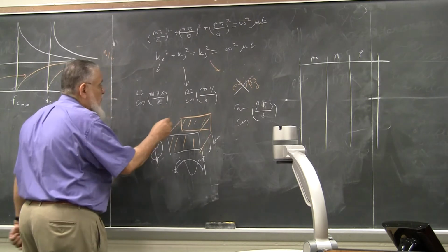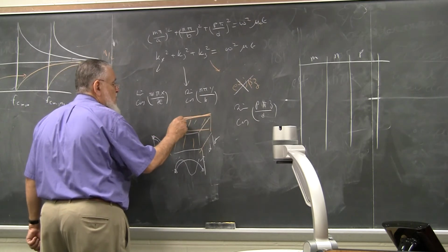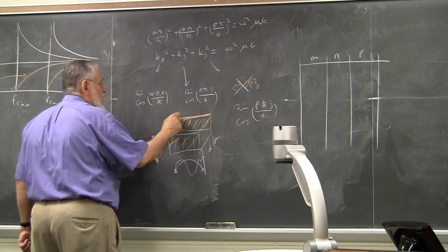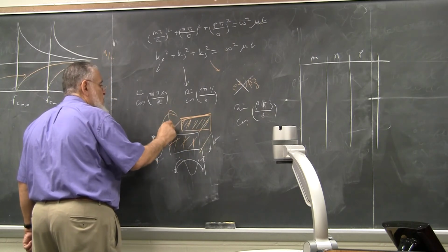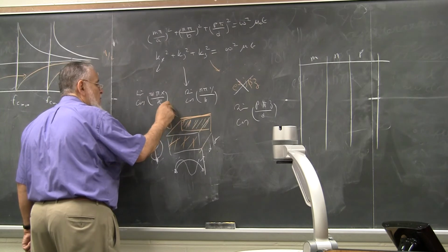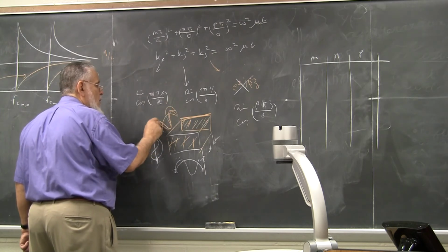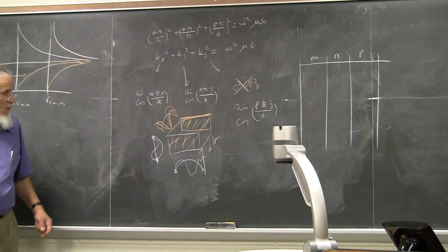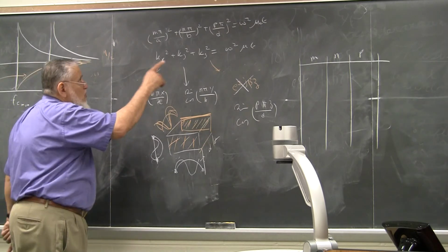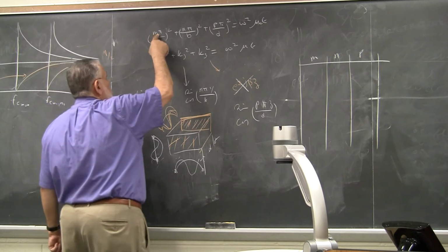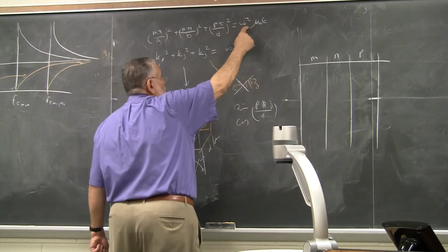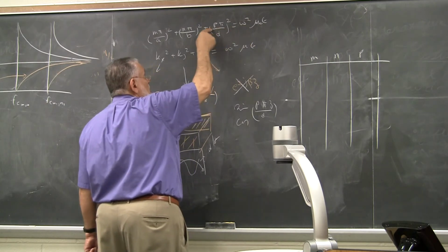On the d also, to meet the boundary condition, that means the field has to be shorted here and shorted there. That means again you have a similar situation, right? To meet the boundary conditions, again, p has to be an integer. So this must be an integer, this must be an integer, this must be an integer. So obviously there will be some unique values for the omega that will meet that condition.